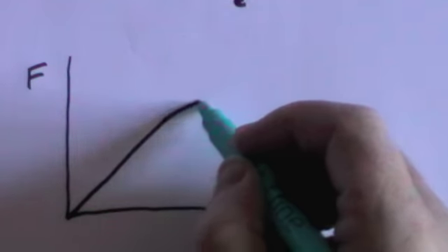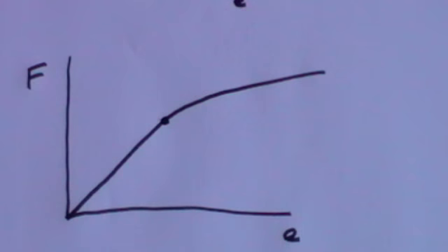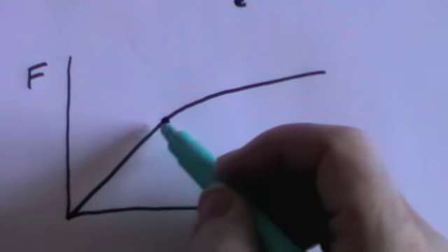So you can always measure the extension and thus work out what the mass or the force is. But if you try and put an elephant on the spring, what will happen is you'll see something like this happen, and at that point, you go beyond what's called the limit of proportionality. Here, you've got a straight line proportionality which says that the extension is directly proportional to the mass.